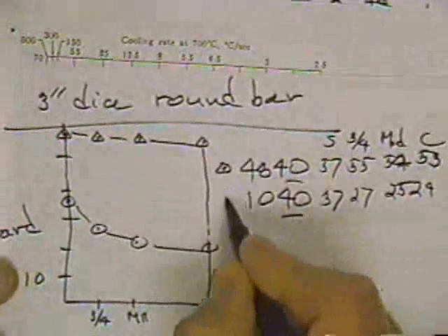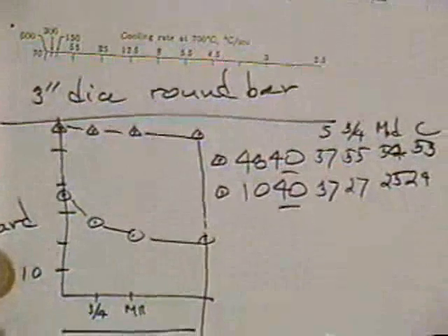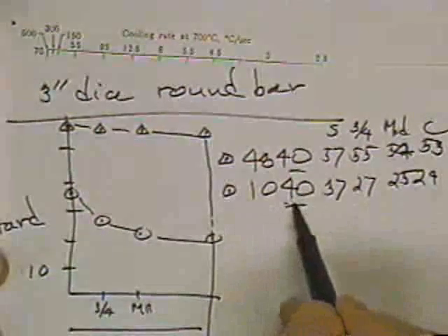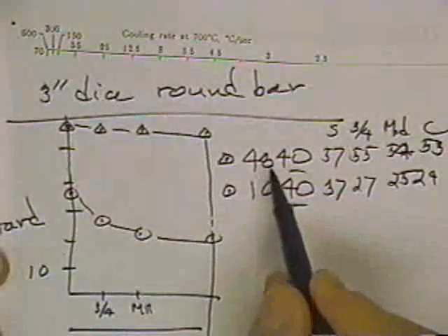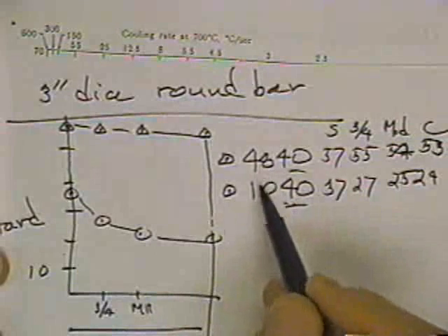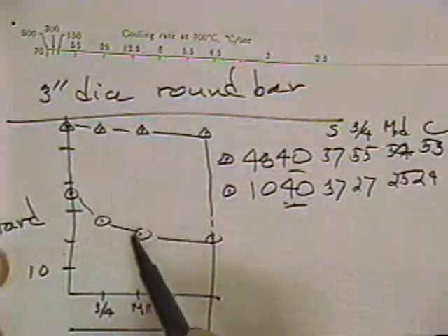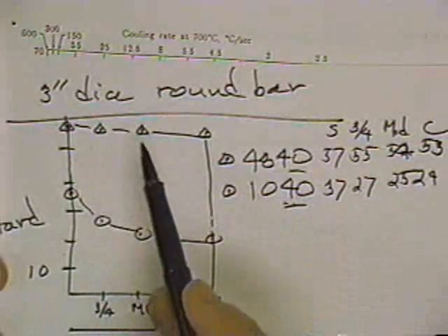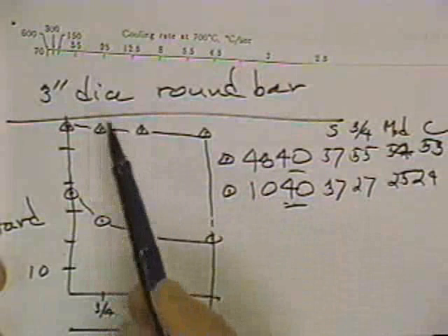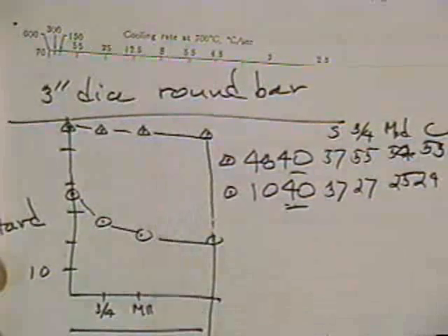So, and this shows you the effect of alloying elements. Same carbon. This has nickel chromoly. It's a chromoly nickel steel, and this has a little bit of manganese. So there's a huge difference in the hardenability. So if you wanted a fully hardened bar, you'd want to choose some alloy steel, not a 1040 steel. So that's how you can use the geometry data and that hardenability data to help yourself make predictions.